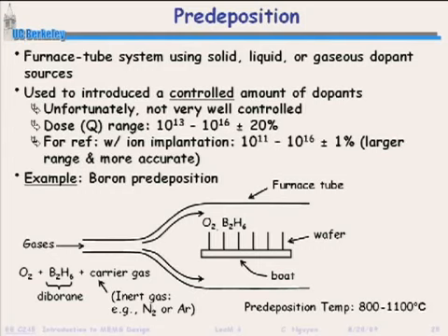But this 10 to the 16th is true in the sense that there's a solid solubility limit for the dopant in silicon. Right, and if you do drive-in, you're limited by that limit. But in ion implantation, you're not. You can dope the heck out of it beyond the solid solubility limit. You're not going to get better performance than that limit, right? Because those dopants, in order to be effective, have to get into the lattice, right? They have to get together with the silicon in the lattice. But you can dope it heavier. You can put more dopants in there than the solid solubility limit, whereas you cannot with drive-in diffusion. Okay, you're right on that.